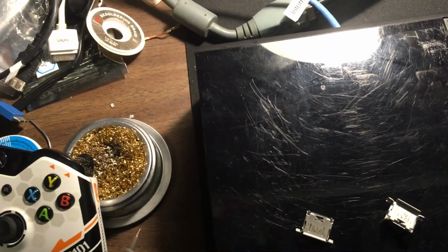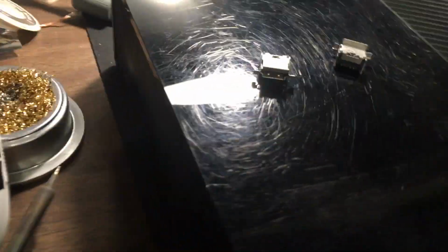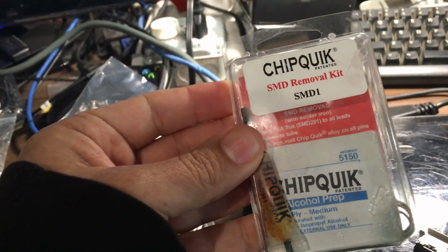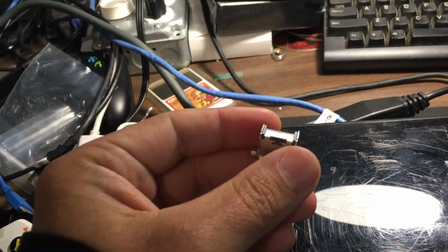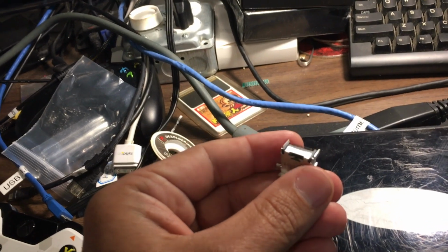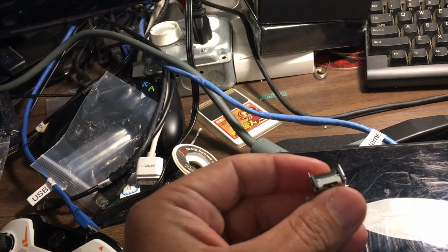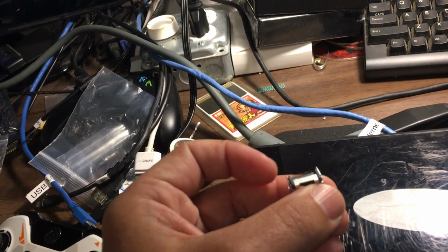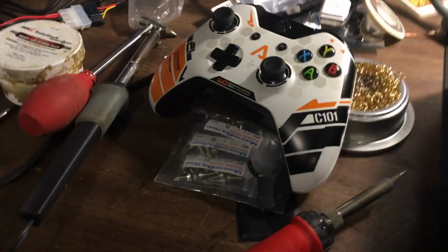I have some low melt solder. I'll bring that out in just a little bit. In fact, let me see if I can grab it really quick out of my bag. Yep, here it is. It's called an SMD removal kit, but this is low melt solder. And the idea is we'll put this on these little pins on the back. Because it's a low melt, it stays in a liquid form for a longer period of time than normal solder. So it's enough where you can basically liquefy all the solder on all 19 pins at once, and the port just falls off.